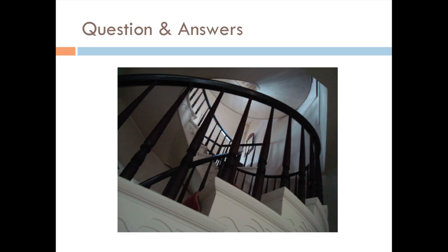There are plenty of buildings you can look at that have been standing for 200 to 300 years without waterproofing products, and they're holding up fairly well without accelerated deterioration. The worst cases that I've seen are where a waterproofing product's been put on the exterior of a building. There are lots of different things that can go on case to case, but as you mentioned earlier, the interior plaster can come off, because the moisture that's already in the wall will try to escape, and it's going to go either out or in, whichever is easiest, through wetting and drying cycles. So I wouldn't use it unless, again, it's below grade or in very special circumstances.